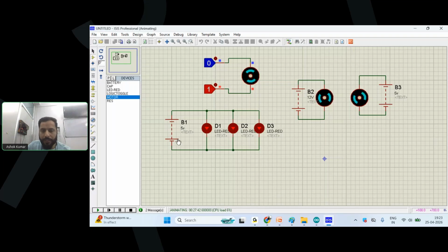So here are two different scenarios. When we have connected the motor directly with the source of 12 volt, we can see that the motor is working in the clockwise direction. But in reality, we can't do this, because if we directly connect the positive terminal of the battery with the positive of the motor, it will always go in clockwise direction. And suppose I want the robot to come back to me, or I want the robot to go left side or right side. Obviously, we need to change the connections at that time. So if we do this using the program, we can customize it anytime when we want.